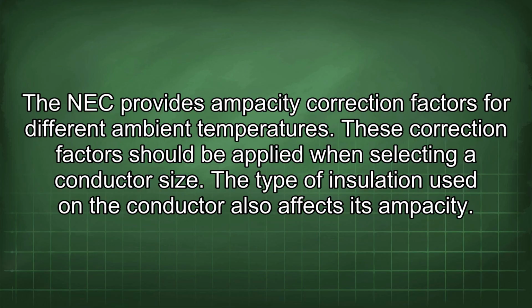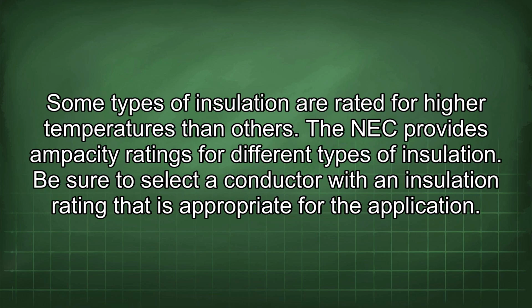The type of insulation used in the conductor also affects its ampacity. Some types of insulation are rated for higher temperatures than others. The NEC provides ampacity ratings for different types of insulation. Be sure to select a conductor with an insulation rating that is appropriate for the application.